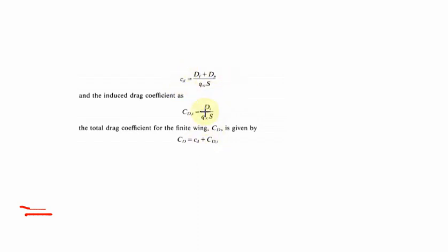That is why we are using the symbol. We have confusion about the symbols related to various factors. For example, we are using L and L dash, and similarly capital CL and small cl. These are things you may have confusion about. Wherever you are using capital L, this represents the total lift value of a wing section. This L dash, L prime, represents lift per unit span. This L represents the total lift for the particular aerofoil wing section.